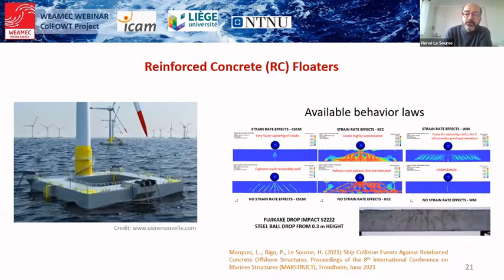For the concrete floaters, the first step has been to set up numerical models in LS-Dyna. So we performed simulation of impact of a rigid striker against reinforced concrete slabs. And the reliability of the proposed behavior laws has been checked by comparison with experimental results extracted from the literature.